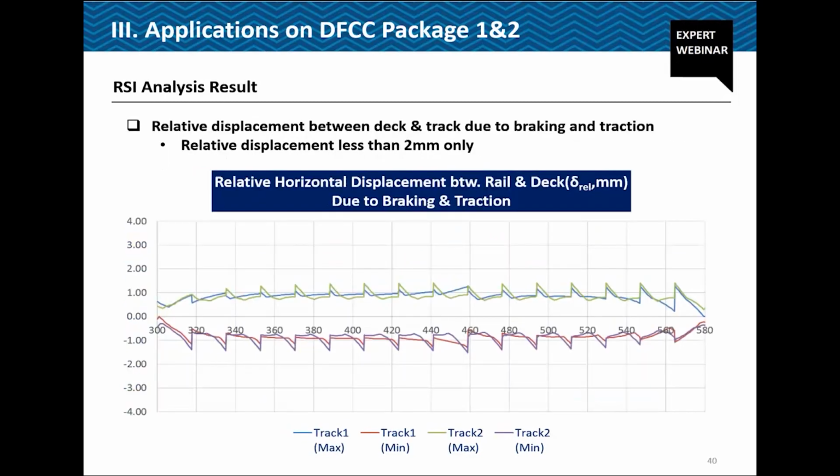This is each PU we checked due to vertical bending also. This limit is 8 mm, but we don't expect any significant problem because this girder's span length is very short and the girder height is quite steep. And so this situation is normal. We concluded the end rotation with such a short span, with a conventional structure in railway structure, is not an issue. Mainly, we found this rail stress is critical.